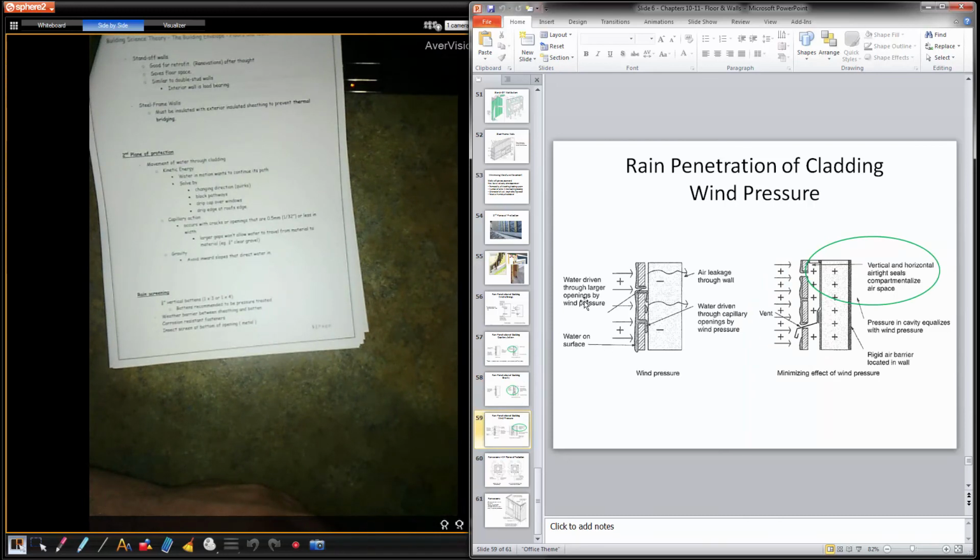This is just looking at pressure, wind pushing in, forcing water to go in. So creating a bigger gap behind products allows for the water to drop, otherwise it kind of gets caught and immobilized and then slowly wants to work its way in. We're going to have a larger gap with good flow. It's easier for it to come out. Water just flows out. Okay.